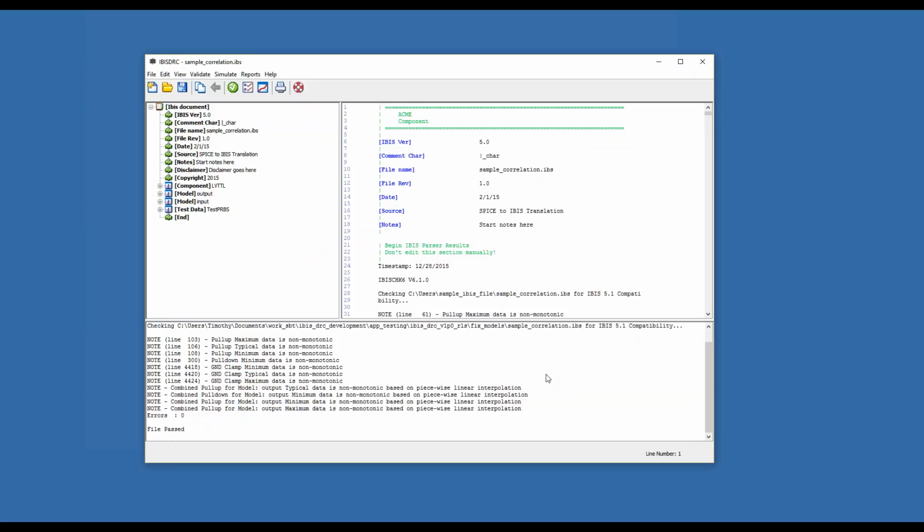And I think as you do more signal integrity, or the deeper you get into it, you're going to realize, if you haven't already, that correlating your simulation model to your hardware is really what closes the loop and gives you the most benefit of doing signal integrity in the first place. So you always want to close that loop. IBIS models and the I/O models that you use are part of that, just like your PCB impedance and transmission and S parameter models, all that stuff. You need to close the loop, make it so it all correlates, and make sure that you understand how every piece in your flow works.